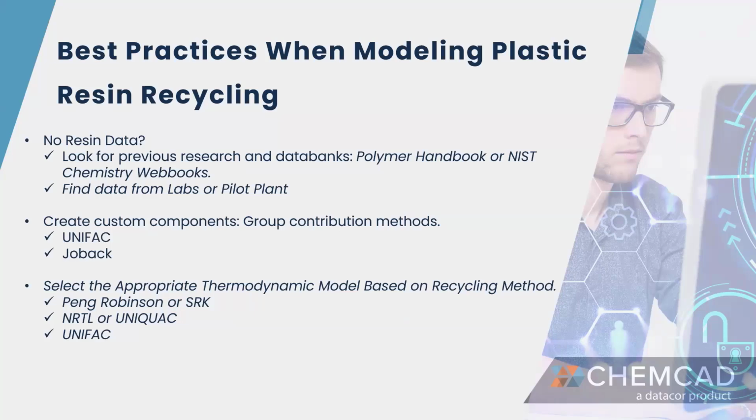NRTL or UNIQUAC might be useful if you have experimental data available. And UNIFAC when you don't have any data available, so you can have a predictive model to help with the calculations.